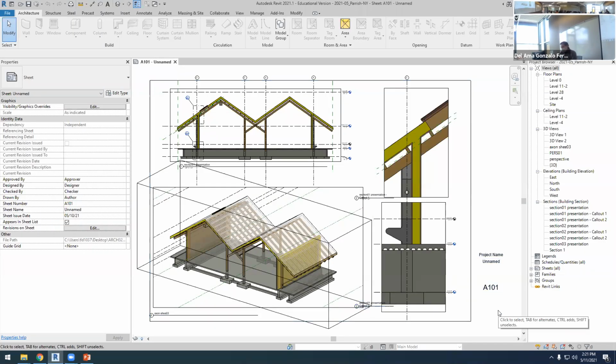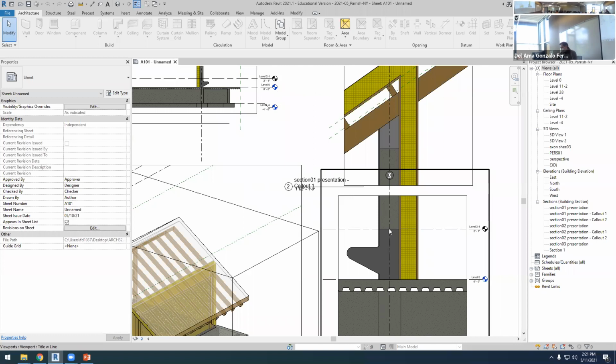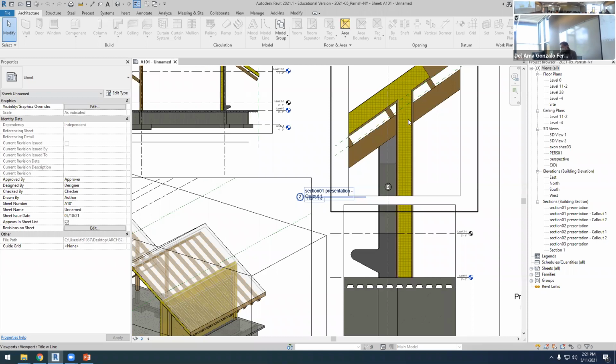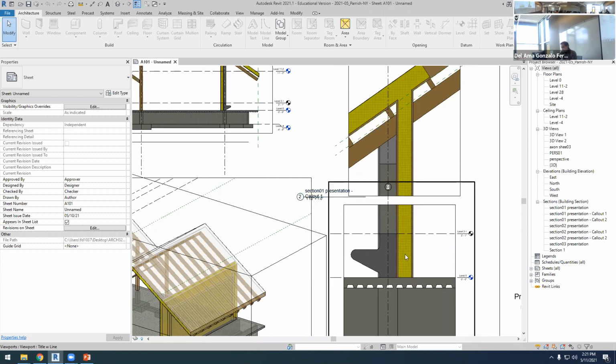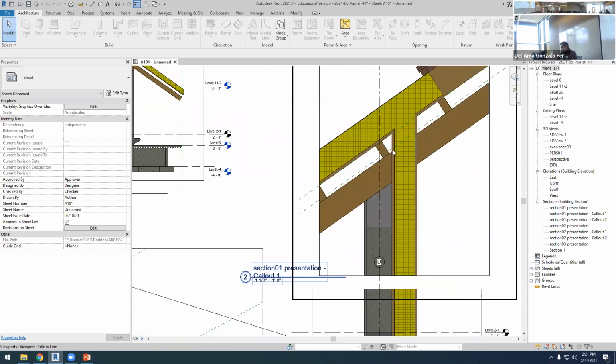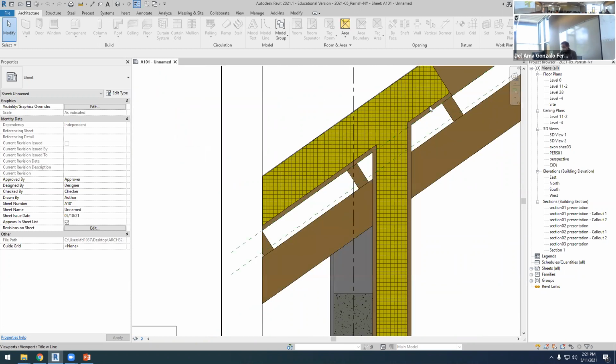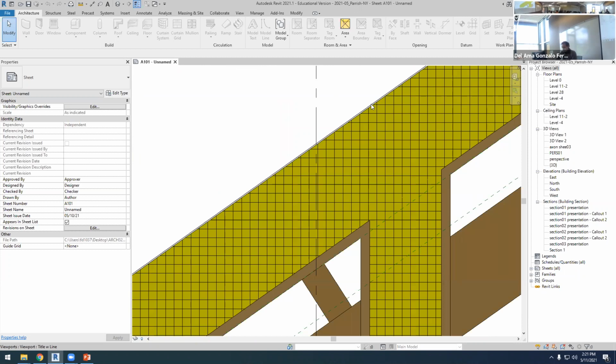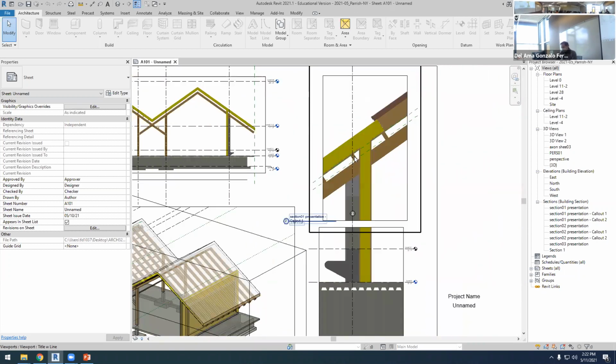This is the Parish Art Museum, and in the video I showed you how to get to this point. Here in this museum we have something different, because there are parts in which we have a concrete wall with a bench like this, and then we have the regular wall. This wall has wood and thermal insulation, and it is the same thing we have in the roof: the wood, the thermal insulation, and then this metal, zinc, or aluminum layer for waterproofing.